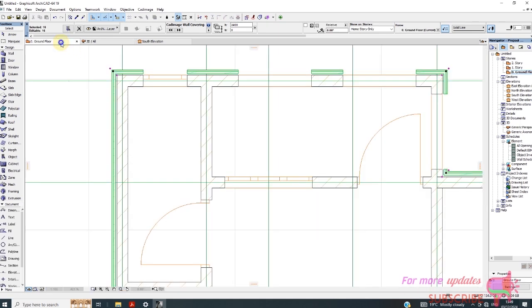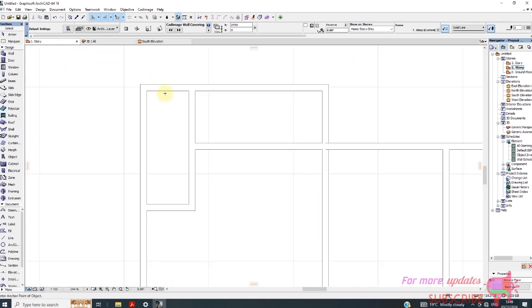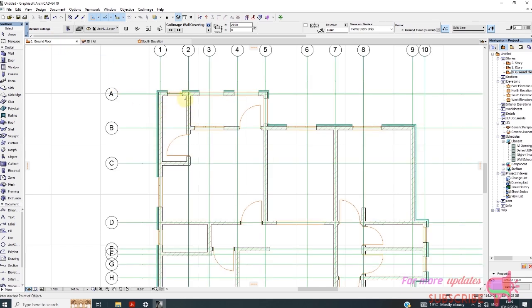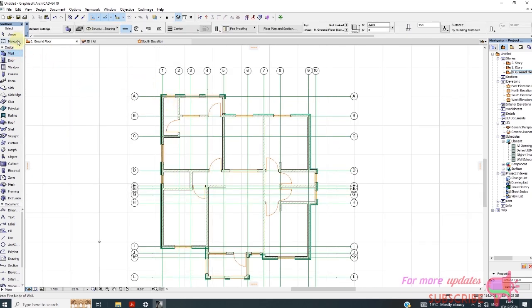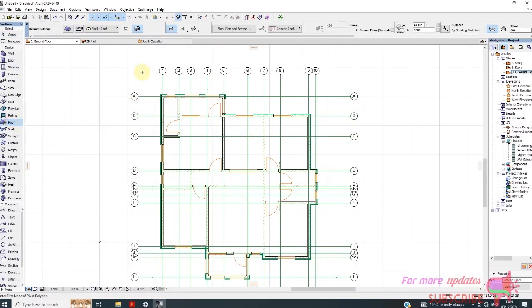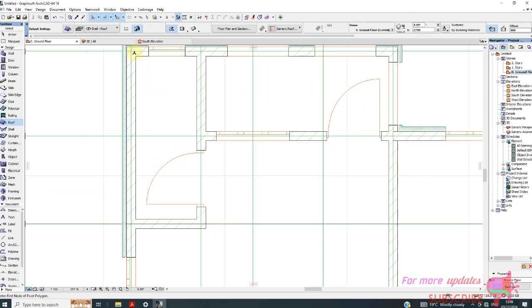now I'll go now to first floor. Just ground floor. I want to insert my roof. So I'll activate roof. This type of roof, complex roof. Now this one, I want it to be 2700. This one, I want it to be 8%. Then from there,